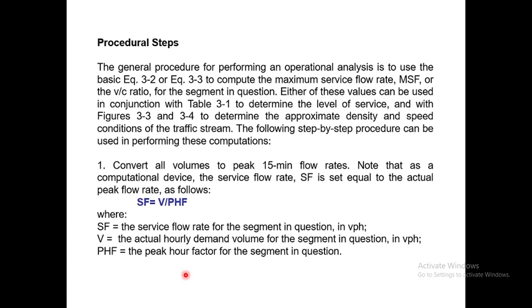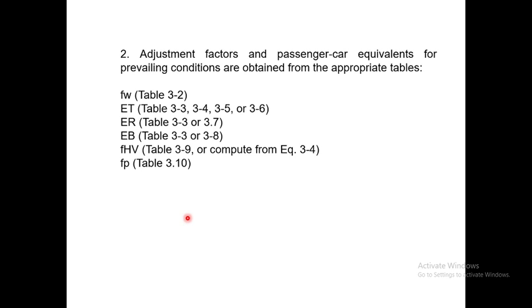So remember, if we give you volume, if we give you demand, like hourly demand, you have to convert it to a peak 15-minute flow rate. We need the flow rate in the scale of 15 minutes. Here you can use this value to convert it. So this is the first step.